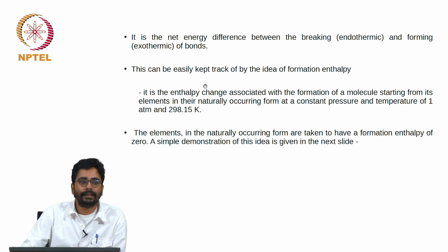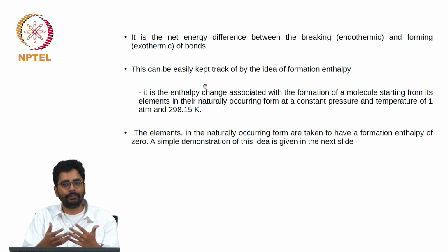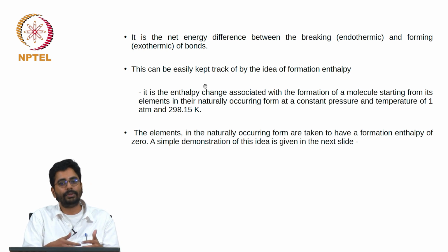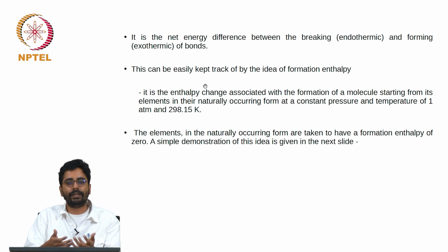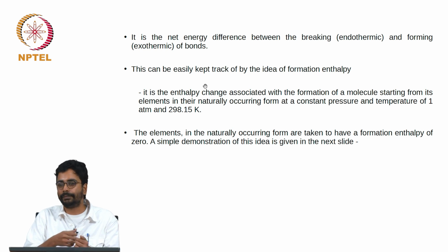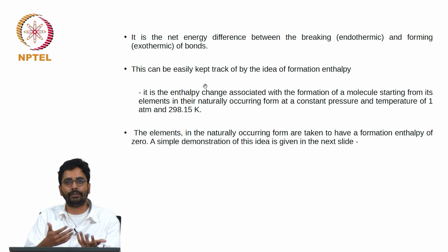Okay. So now we have a variety of oxidizers, variety of fuels depending on whether you are looking at liquid propulsion systems or gas turbines or solid propellant rockets. So there are a variety of oxidizers and fuels. So a simple way to keep track of the idea of this energy associated with reactions is through the idea of formation enthalpy.